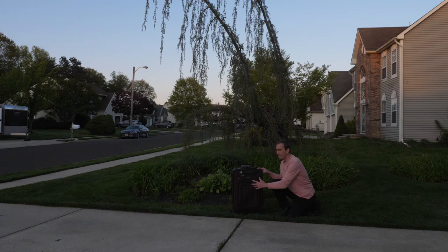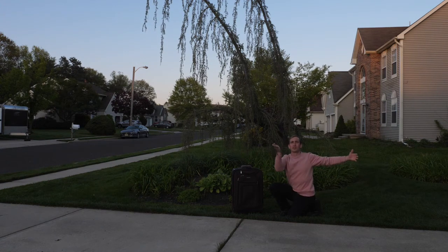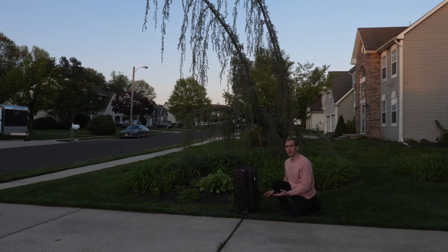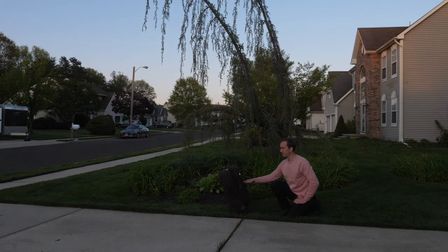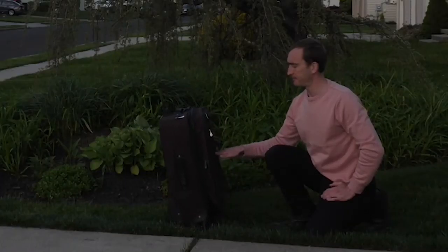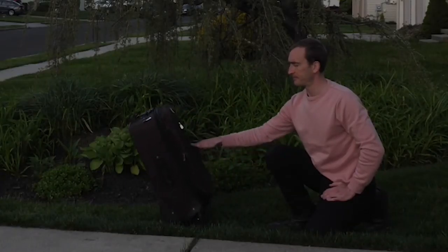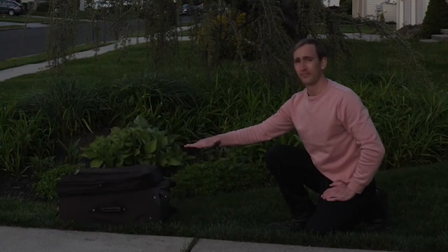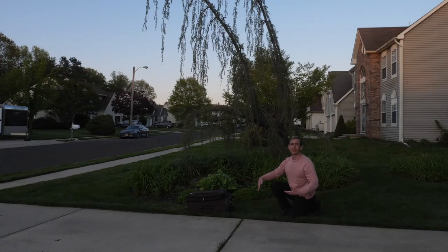So what you can estimate is that if this suitcase got wider and wider and wider this way, the weight would actually be causing a greater and greater resistive moment to rotation. So if I rotate the suitcase this way, what you can see is that even if I apply a force pretty much just at the center of gravity, I cause the bag to tip over so easily because it's very, very narrow. So the resistive moment applied by the gravity is almost zero.